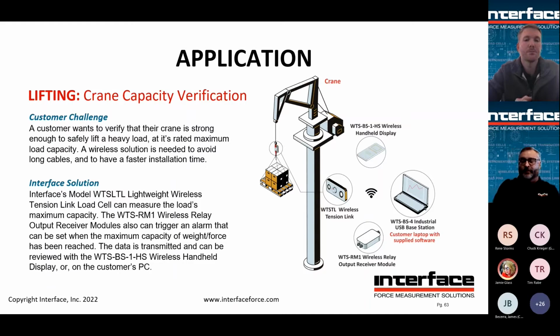And so the nice thing about something like this is you can install something like a tension link, or any of our load cells, a low profile load cell with clevises and rod ends, or a tension link, or one of those shackles we showed. Just kind of depends on the level of accuracy required. But you lift anything up, use the inline sensor as a reference.